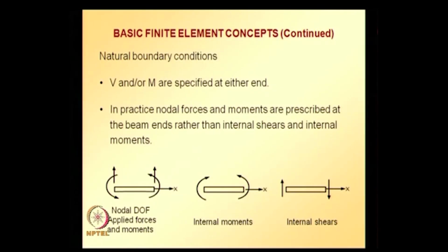If you compare the sign conventions, the applied moment at the left hand end is in the opposite direction to the internal moment at the left hand end, whereas at the right hand end the applied moment is in the same direction as the internal moment.